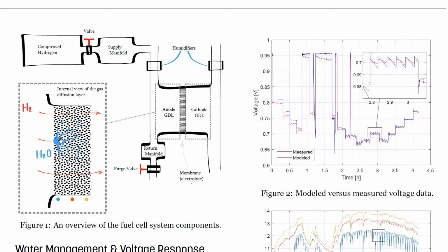And this is not very good because we have these droplets that develop at the gas diffusion layer surface. And so what happens is that when hydrogen is supposed to diffuse through the layer, we get blockages basically. So effectively we are reducing the gas diffusion layer area, or the fuel cell area.